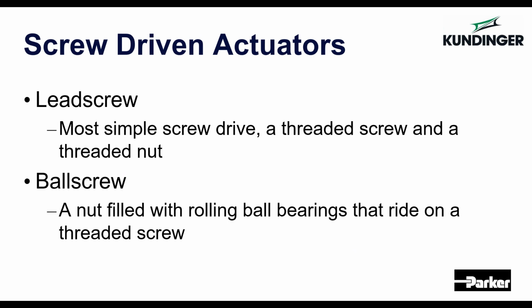So screw drives are typically more costly than belt drives, but they do have an inherent reduction, which means you generally aren't going to need a gearbox. So it can kind of sometimes be a wash cost-wise, depending on what you're trying to do.